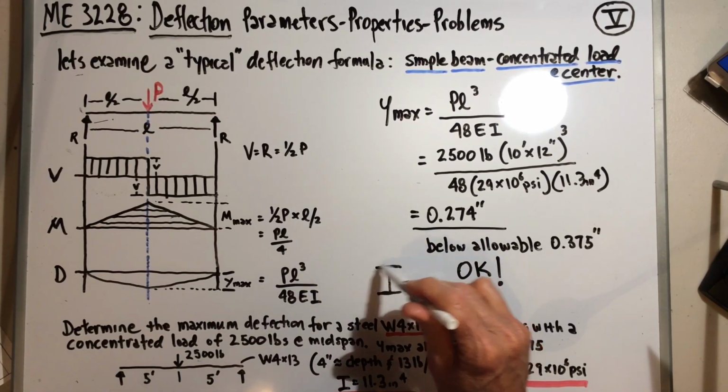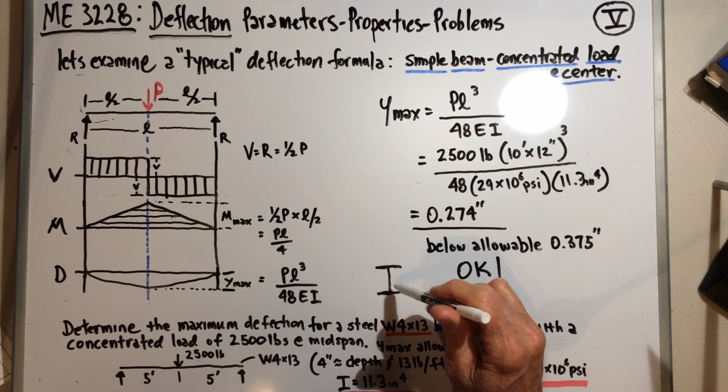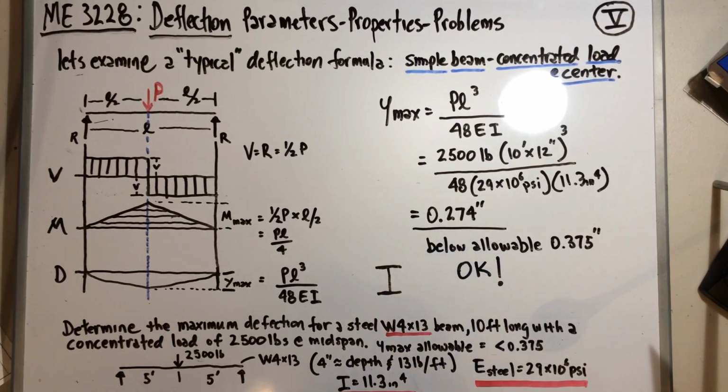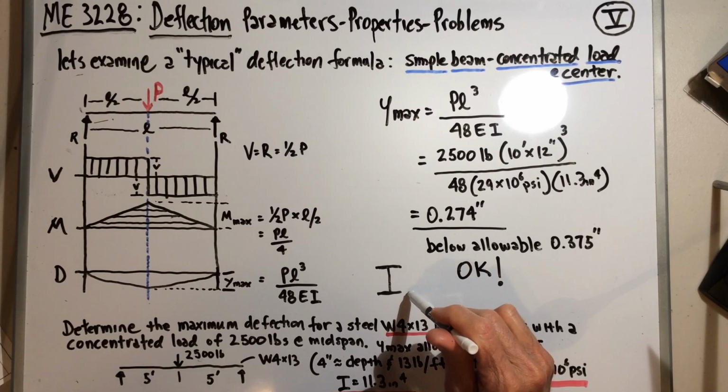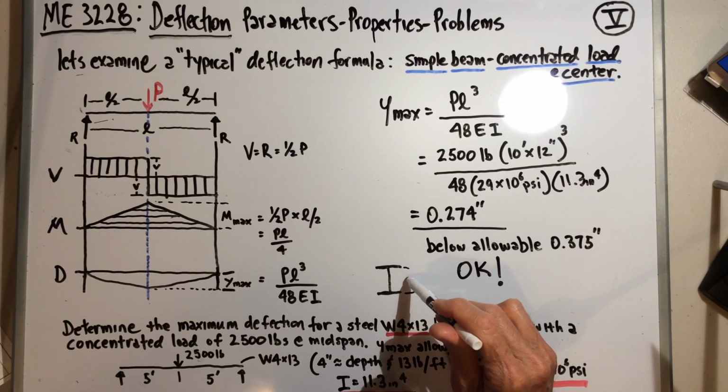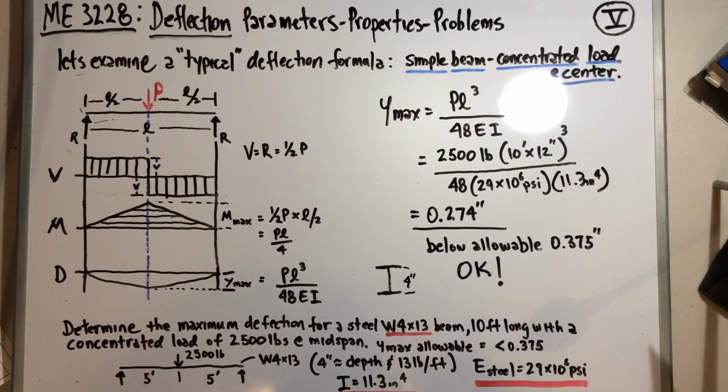And of course, the top portion and bottom portion would be the flanges, and the vertical portion is called the web. And a W4x13 means that essentially the basic depth of this would be only 4 inches. All right, and then the 13 stands for the weight per foot. So it would be 13 pounds per foot and a 4-inch deep beam, essentially.